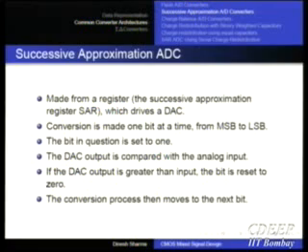I will have a reference which is composed of a variable which is then coupled to a D2A. This is the basic idea, right? Anyway, this doesn't need a diagram, otherwise I have to keep skipping back and forth, right? Quite simple. Since I need a variable which can be shifted up or down, your reference voltage needs to be shifted up or down depending on the previous bit.